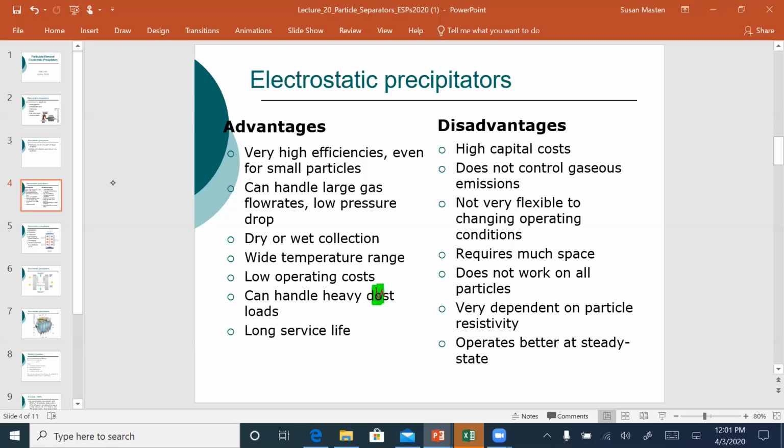Well, then they switch to low sulfur coal. And when they switch, the coal dust, the fly ash actually had significantly different properties, and they got much poorer removal of the particulates and the SO2 on the particulates. The SO2 that was in the gas phase, it didn't affect that, but it did affect particulate removal.